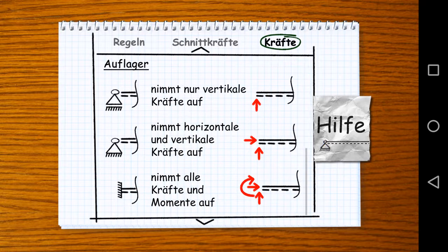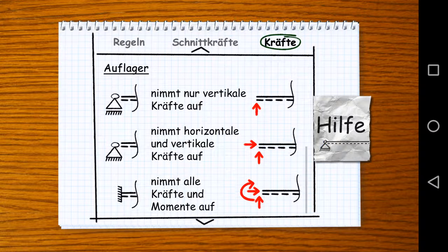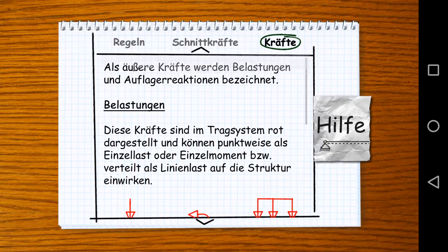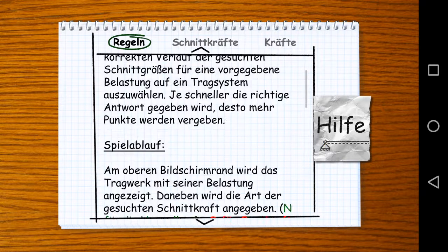Okay, and now here we just want to look at some kinds of supports. We have the roller support, the upper one, with just one force upwards. It could be upwards or downwards, it doesn't really matter. And the pin support with two reaction forces, and then the clamp support with all three reaction forces. Not all of them, but those are the supports we generally get in a 2D case. So let's go and try to actually solve something with all what we've learned.